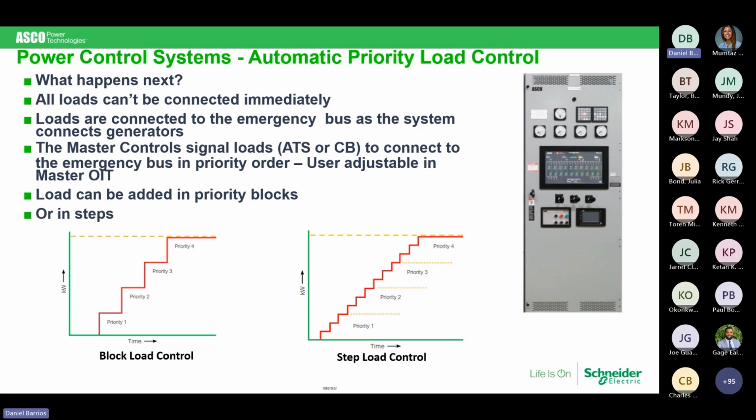In the case of this here, you would then set the priorities further up, priority 2 and 3, so that you put chiller 1 on. You may wait 5 to 10 seconds, put chiller 2 on. Each time you do that, you're giving your generator time to dip and recover. Most of the sizing programs that I've seen, the acceptable dip is about 20%, unless you're looking at a fire pump application. Then you're limited to a 15% voltage dip. Please check me on that. That may have been updated some since I saw one of the programs.